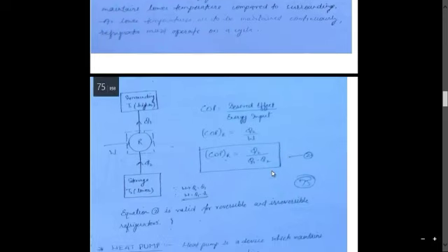So this desired effect is fulfilled by extraction of Q2 amount of heat, divided by the work input, which is our energy input. So COP of refrigerator is equal to Q2 by W, and by the energy balance equation, W plus Q2 is equal to Q1. Therefore the work input is equal to Q1 minus Q2, and COP of refrigerator is equal to Q2 by Q1 minus Q2, right? This is the COP of all refrigerators, whether reversible or irreversible.